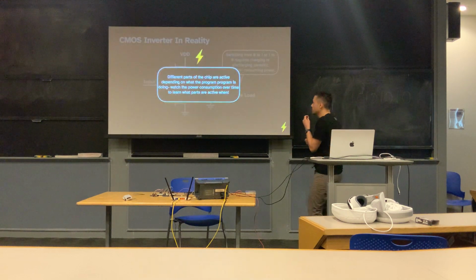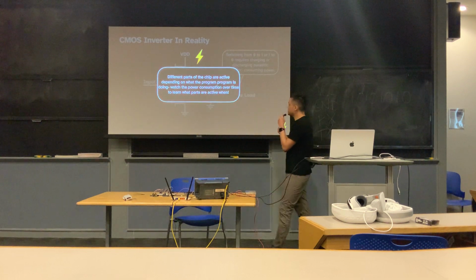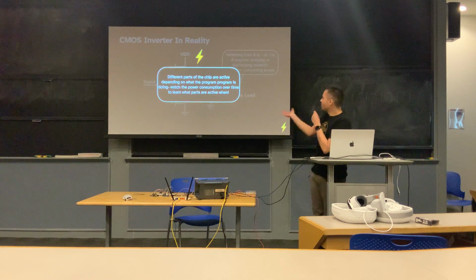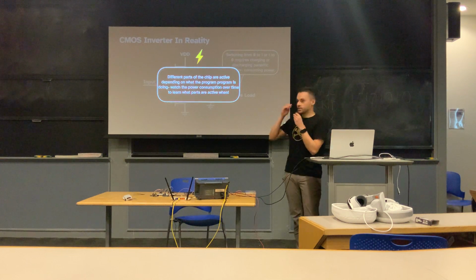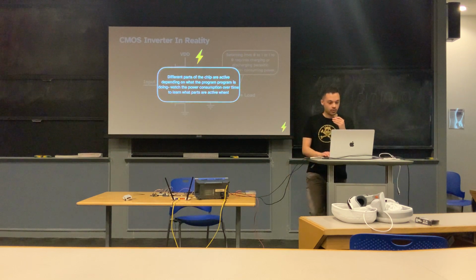So the key takeaway: different parts of the chip are active depending on what the program is doing. I said the word program twice, it's that important. You can watch the power consumption over time to learn what parts are active at what time. Does that make sense? Cool.